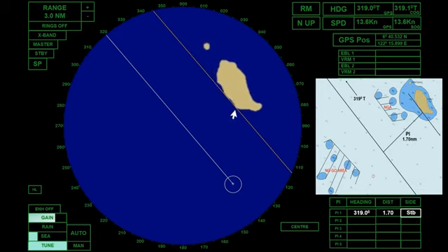As we know, GPS is subject to some interferences, thus giving us position inaccuracy. This navigation technique is very useful to the navigator as it gives a continuous monitoring of the ship's position along the intended track. Even though this technique is used, regular intervals of fixing the ship's position should always be done as stated in the passage plan.